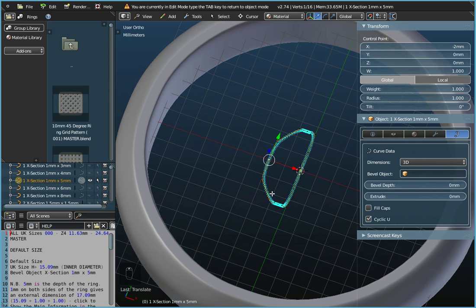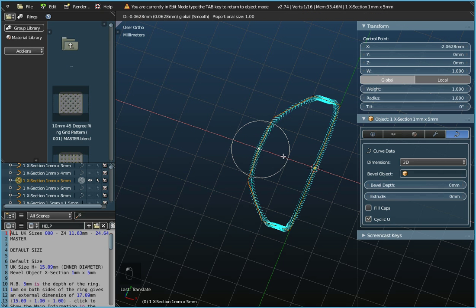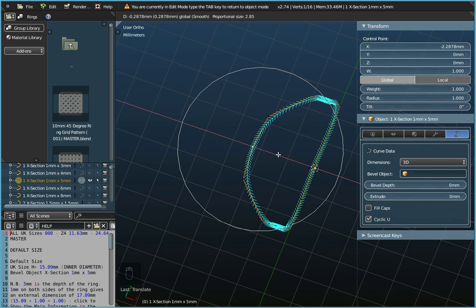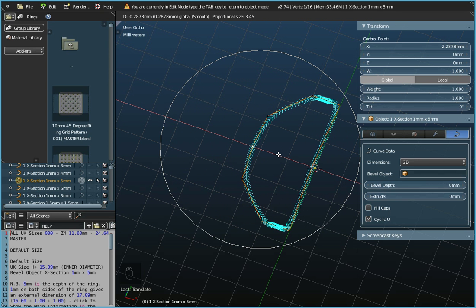Okay, so you can zoom in, and if you want to do it in fine detail, rather than jumping in increments, what you can do is switch off the snap, and there you can control it, you can move it much more smoothly. And if you use the proportional editing, I'm just scrolling the center mouse button to change the proportional editing, that will also smooth it all out.